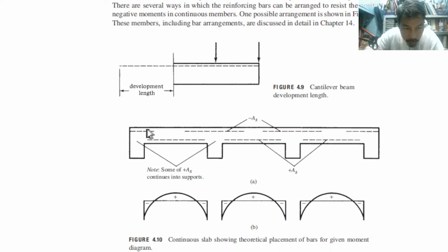So this is the tension bar, then stop it there, then bottom bars here. This is also a tension bar. Here, this is also a tension bar, but this is now top bars, bottom bars, top bars, bottom bars, top bars. They are all tension bars because this is a continuous beam. In the middle of the span, those are tension, tension, tension.